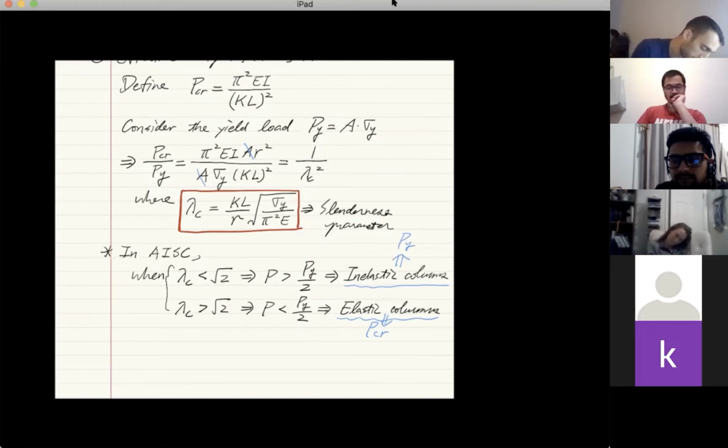But when you look at the relationship between loading and PY, you understand that it's not exactly like that, right? We said that, in fact, in theory, when we consider an elastic column, that means the loading should be greater than PY. But in practice, did we use PY? We didn't use PY. We use what? We use only half of the PY. And why is that?